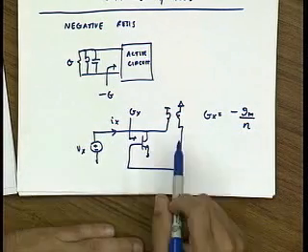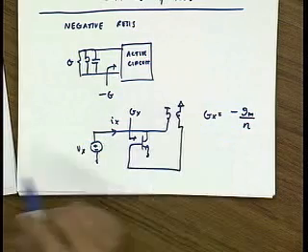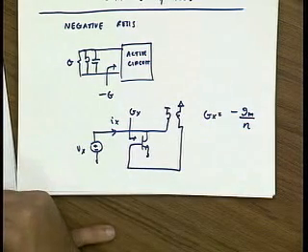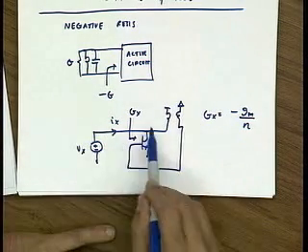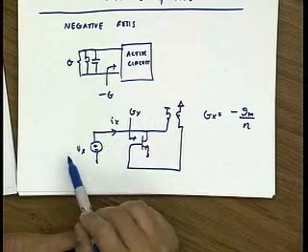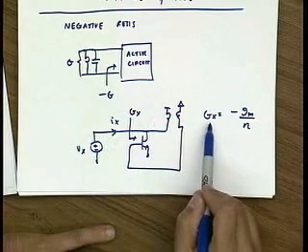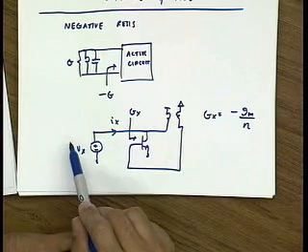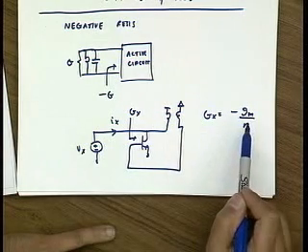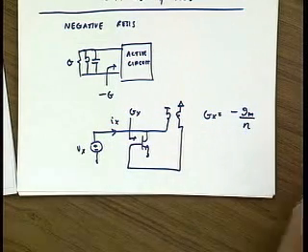We also showed that this perspective for this particular oscillator is equivalent to the loop gain perspective, because to make this resistance larger than the loss of the tank, that requires Gx to be larger than, let's say, Gt, which is equivalent to Gm R tank over N greater than 1.